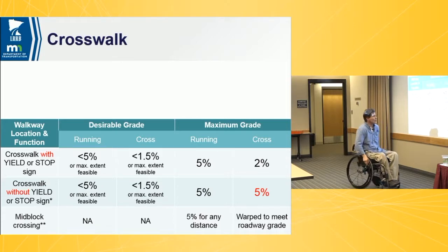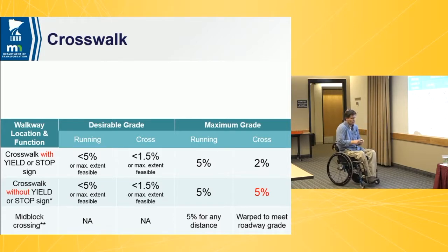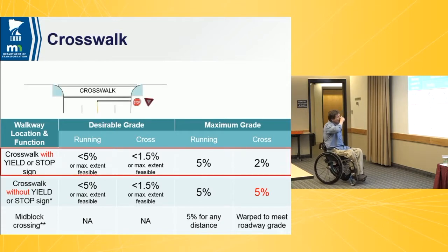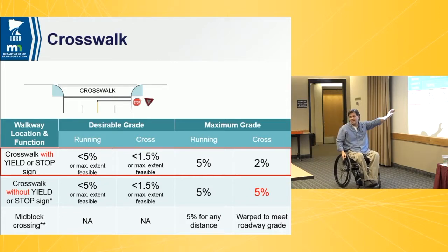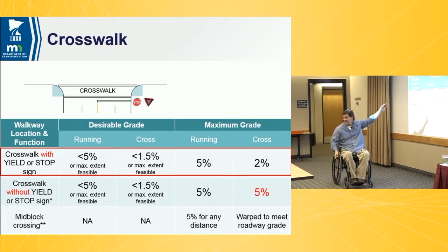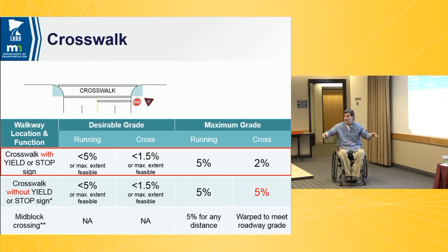They also talk about cross slope being very important. So we'll go into a few cases here. PROAG talks about the first condition where it's a crosswalk with a yield or a stop sign, 2% cross slope. You know, that makes sense. The whole crosswalk can be at 2%. Vehicles are stopping. It doesn't matter. It can flatten out or not flatten out. They're all going slow. So just table the whole thing so the pedestrian going through the crosswalk can have that 2% cross slope. So it's just like sidewalk criteria through your crosswalk.